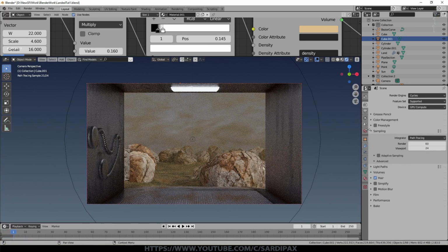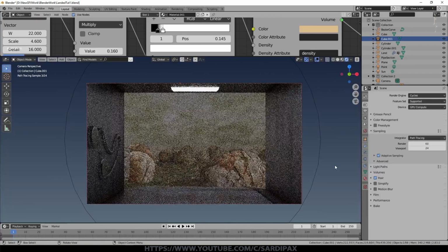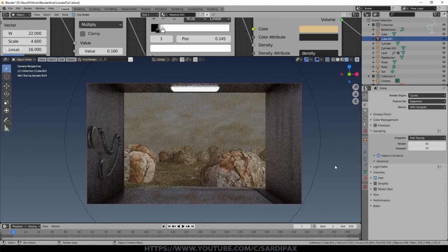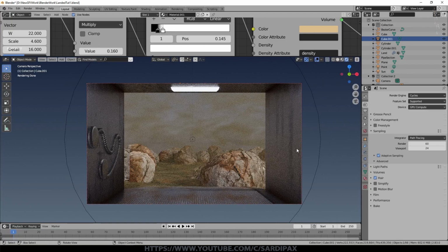We'll render it in a moment and then work on reducing that noise, because that also reduces the visibility of detail. And because this is a still image we're creating, we can be a bit more aggressive in the noise removal. One of the things that's worth doing though is turning on adaptive sampling. This does seem to affect the viewport as well, and what it does is it just makes Blender vary the amount of samples that it gives to different areas in order to optimize the reduction in noise. So it doesn't necessarily do the full number of samples that you've set. It will do where it thinks it's particularly noisy, perhaps where there's a lot of dynamic range over a very small area, but where there isn't, it doesn't need to spend a lot of time doing that. So it optimizes the time.